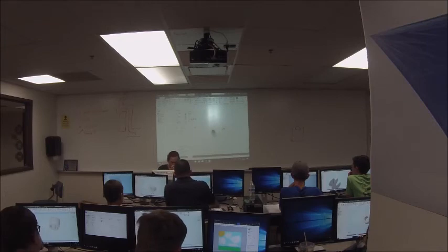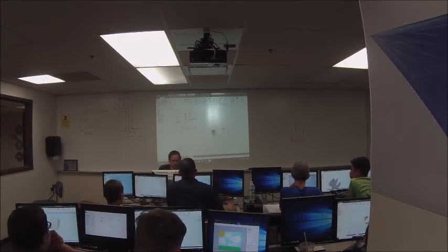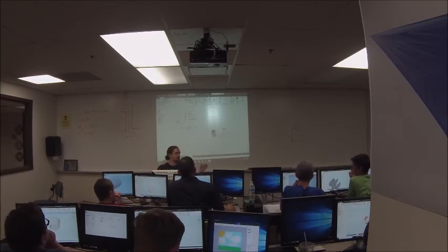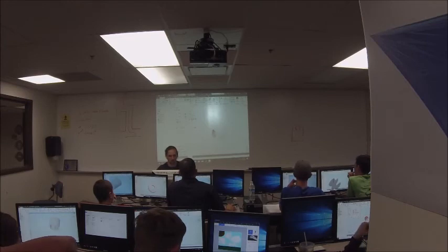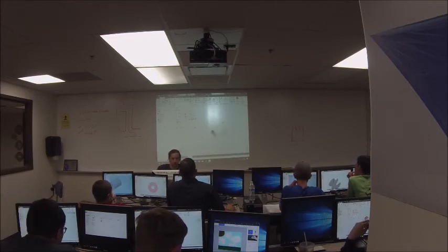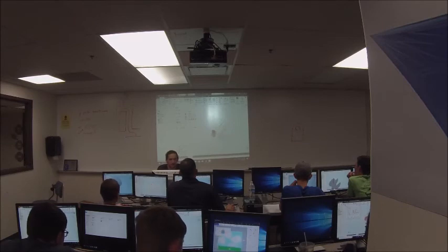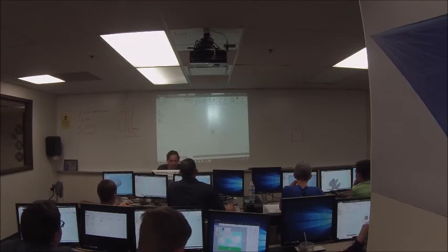Now I can set my depth. It just happens that I extruded it 2 inches long. It remembers the last number you typed in there, so it's wanting to cut 2 inches deep, so it's going all the way through the part, which might be fine if that's what you want, but I just want it like 1.5 inches. Okay, so you can finish the sketch, and I kind of make it like a little cut. That might be useful for something.